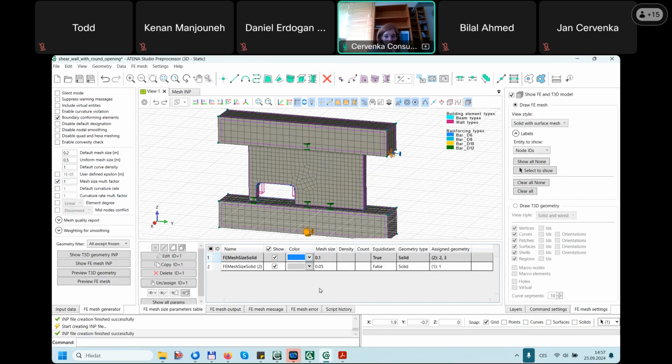If you have more specified sizes of the mesh throughout your geometry, you can use this multiplication factor for all of them at once, so you don't have to manually go through all of the settings and change them. For example, you can see what size of mesh I have in here, and if, instead of 1, I multiply it by 0.5, it should make a smaller mesh everywhere because it's multiplying it. So this is the factor that you can use all over.